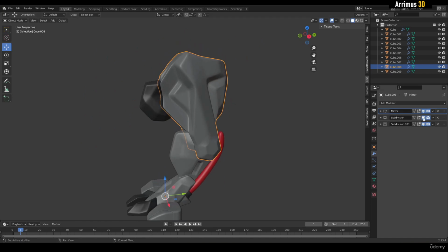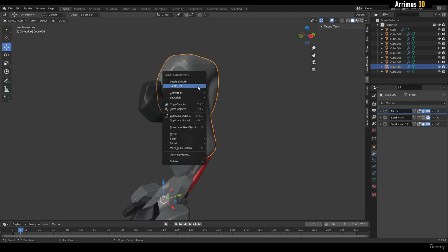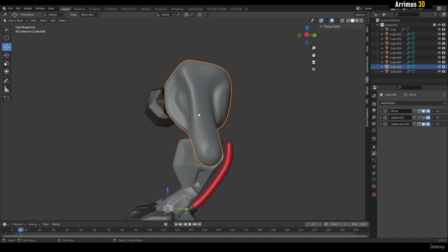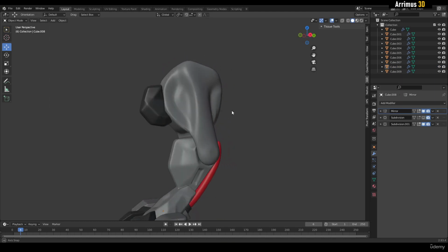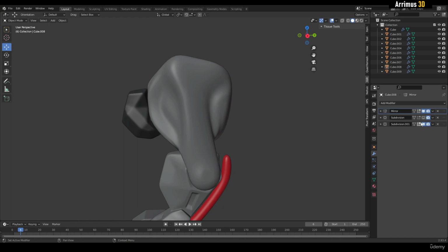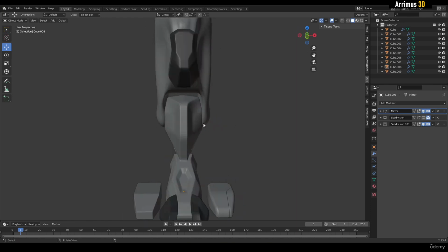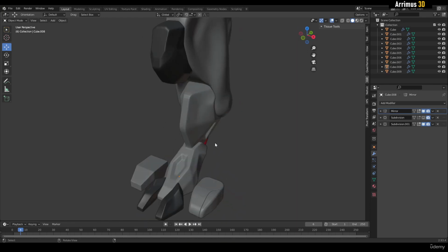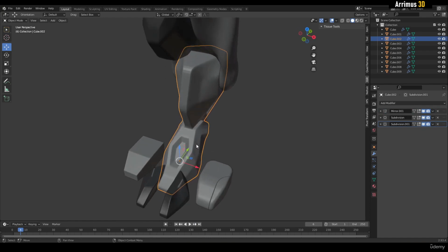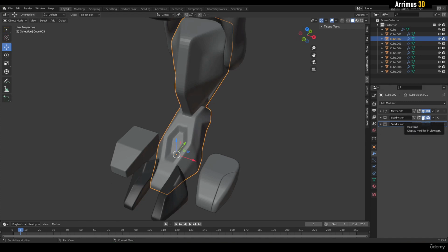What you can always do is you can always turn off this one, for example. Now we've transformed the object from the angular freeform to a more smooth freeform. So just by turning this modifier on and off, we can actually modify how the object looks. So if you're done working with this, you can treat this as a base mesh. And when you're ready to start working with some loops and some more advanced details and to start introducing more curves into here, you can simply just turn that off right there.